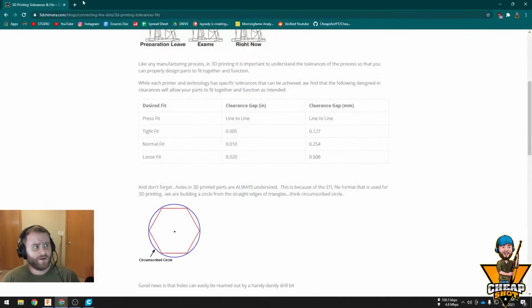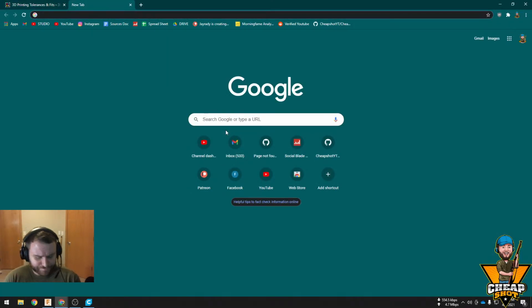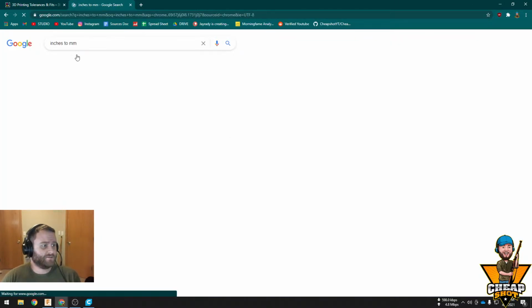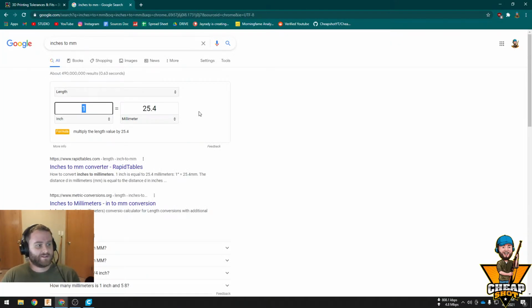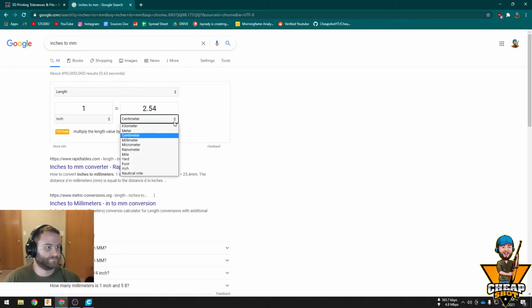Why is this a thing? Why 2,540? Well, going from inches to millimeters, 1 inch is 25.4 millimeters, so I need to go 2,540% bigger. Or maybe it's because it's centimeters. Whatever. If you load in a print and it's too small, first try 2540. If that looks too big, then chances are it is in a different metric system. Just go to 1,000, and that'll fix it perfectly.